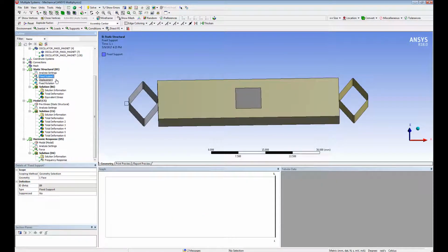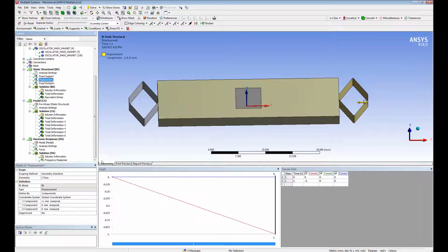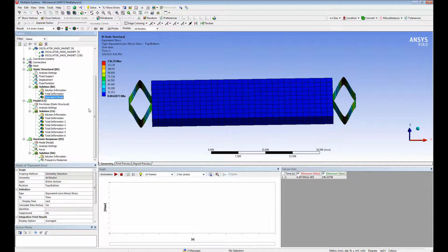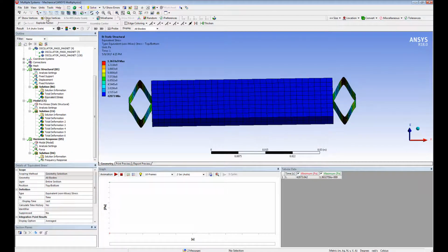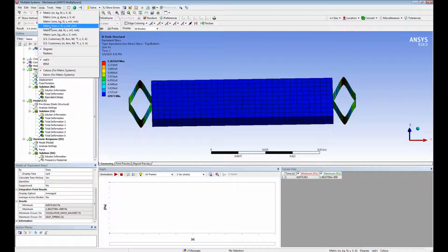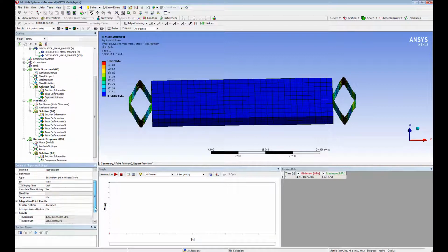I'm going to leave the compression displacement constant for now at 1 millimeter, and I want to take a look at maybe the pre-stress, maximum equivalent stress due to that loading. Interesting set of units here. So let's switch to, say, megapascals. So we have 1,000 megapascals as our pre-stress, maximum pre-stress here.